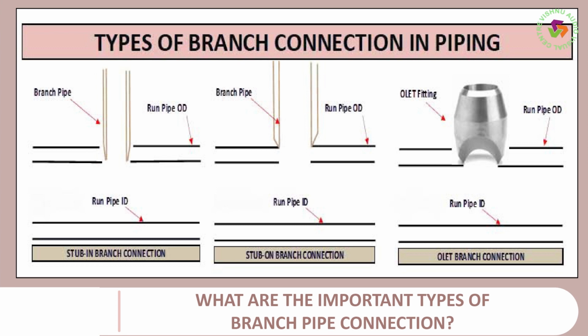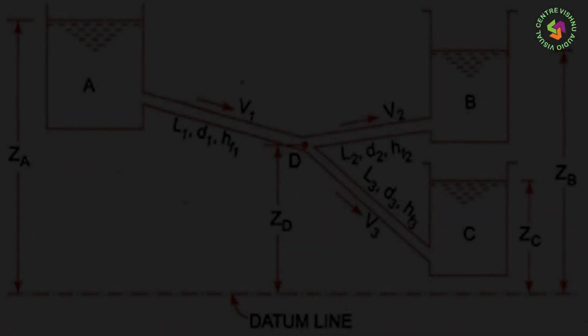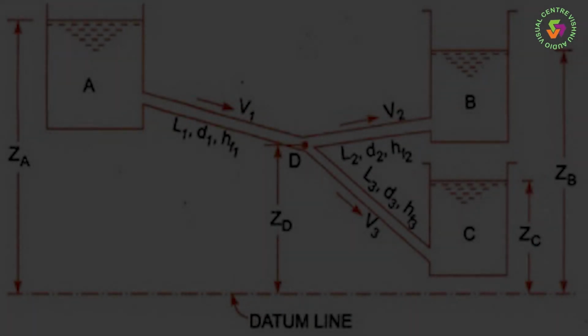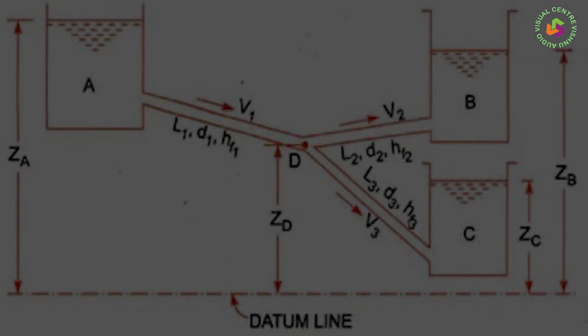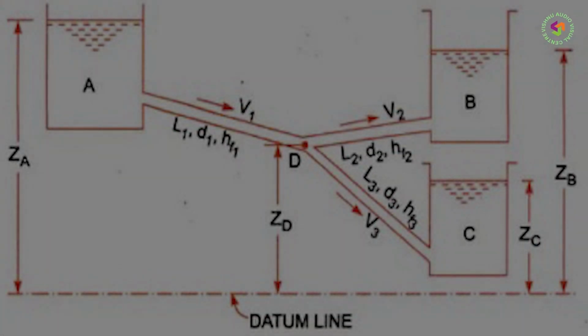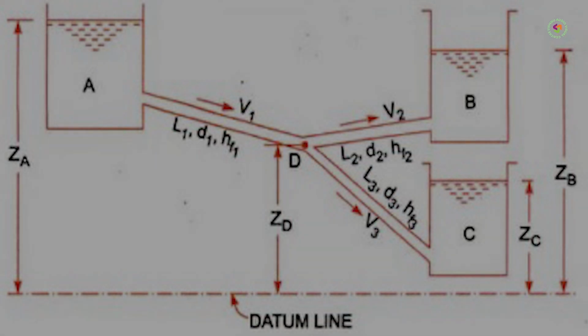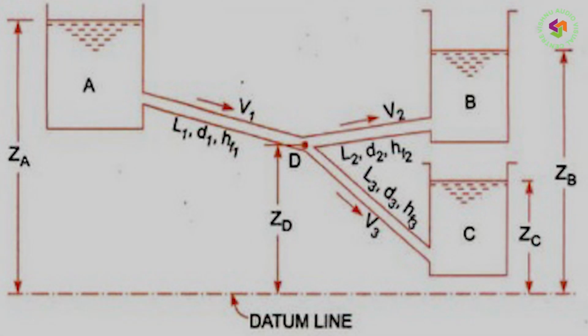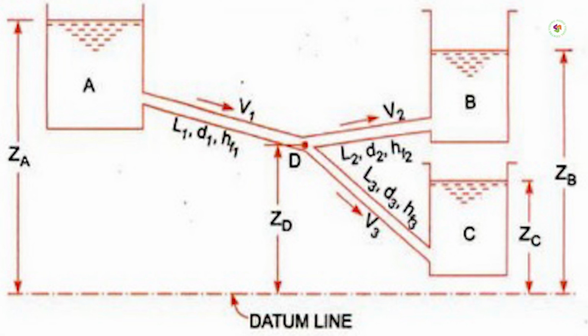If it is still not 0, then again a correction has to be applied, and with this new correction, the discharge has to be modified in each pipe. After modifying the discharge, we do the same again. This process is repeated in each loop for each pipe of the loop till the net head loss in each loop is equal to 0. So that was what we mentioned in the morning.